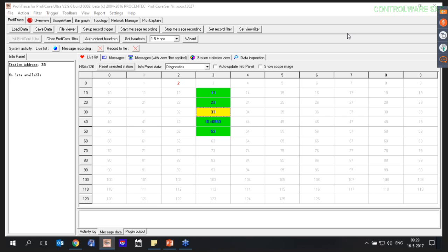You can see the distance to your device if you switch on this termination. But you really need to know what you are doing, because if you switch on this termination, the amplitude of your signal gets lower and your installation can go down. So if you don't know exactly what this means, just don't use this termination. Always keep it off.